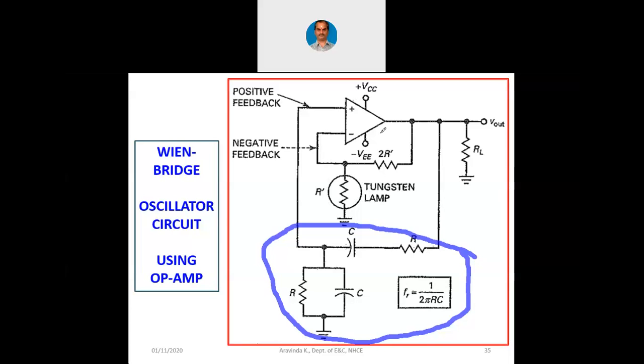But you know that for the operational amplifier, we have these gain setting resistors, right? When we have these gain setting resistors, in the earlier circuits, we had some requirement on the value of A. Now in this case, we have no such requirement on the value of A. Actually, we can have a gain also along with the oscillation. That's why you can see 2R' and R' is there, which means this op-amp can be used to produce 2 times the voltage gain.